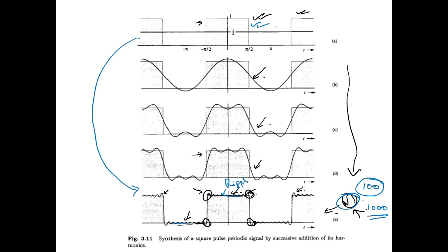These ripples get more pronounced at the discontinuities, where the value goes from 0 to the maximum. Not only on the upper side, on the lower side also, there is a slightly increased change in the amplitude levels. This phenomenon is regarded as the Gibbs phenomenon.